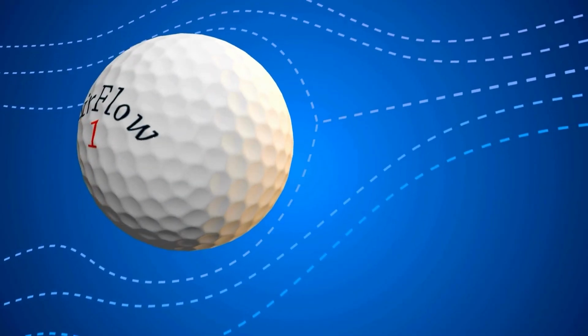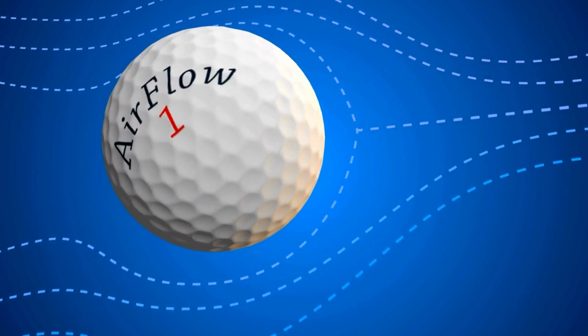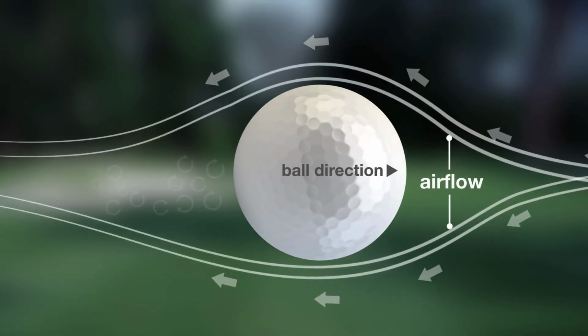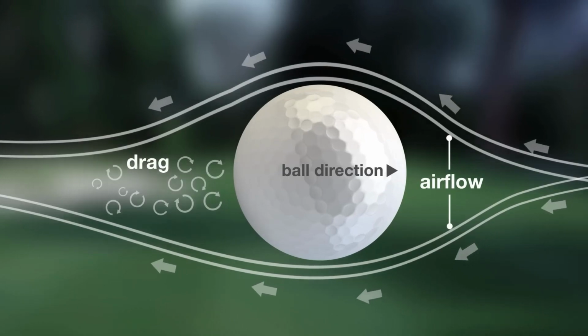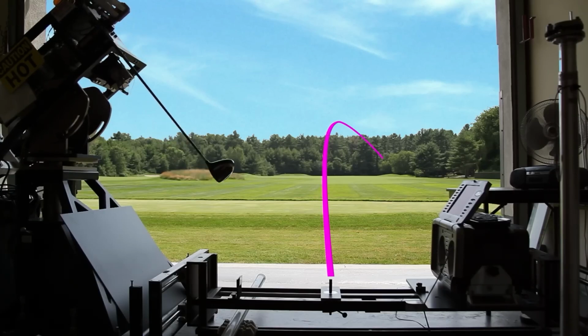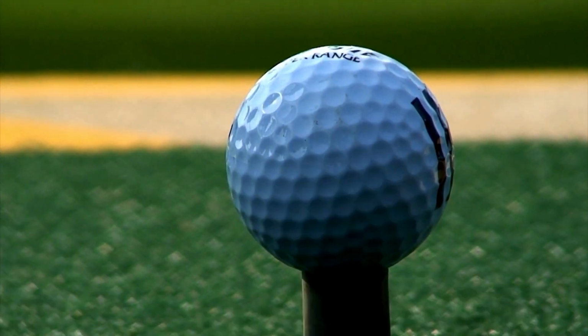The size and depth of the dimples play a crucial role in determining the flight and behavior of a golf ball. Shallow dimples. These create more spin, which increases lift and keeps the ball aloft longer. Consequently, the ball has a higher trajectory and less roll upon landing. Deep dimples. These generate less spin, resulting in a lower trajectory and more roll after hitting the ground. This is beneficial for achieving greater distances on low shots.